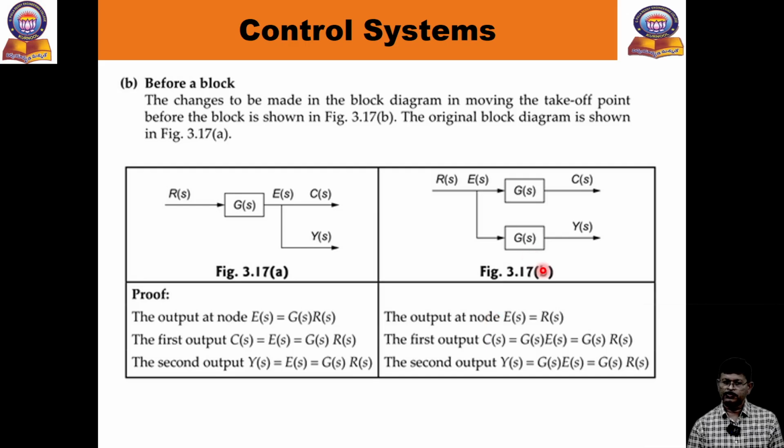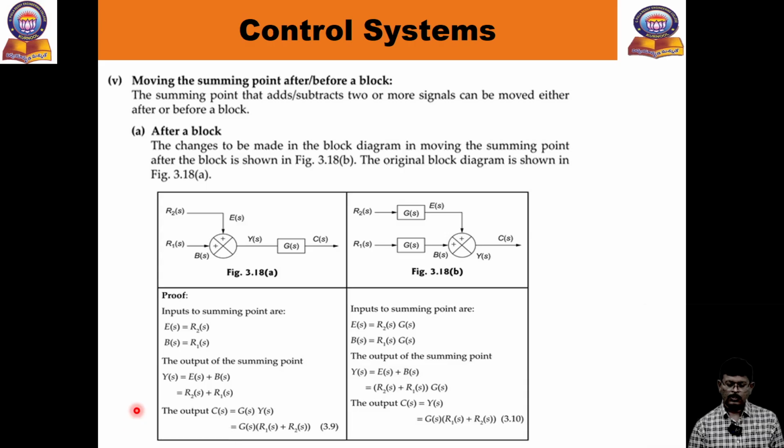So that is the difference between the pickup point when you are shifting it after and before. Then the same thing applies to moving the summing point, before and after. Now take this summing point.